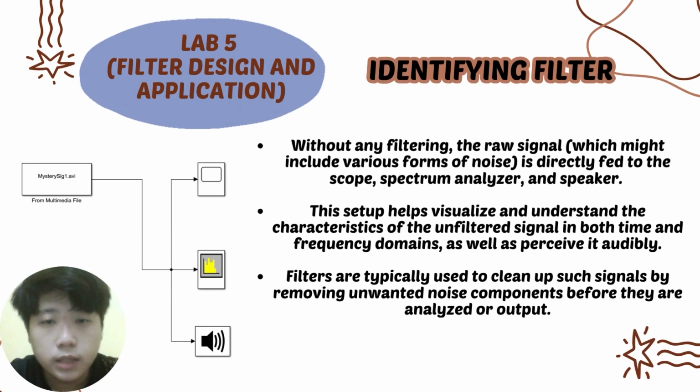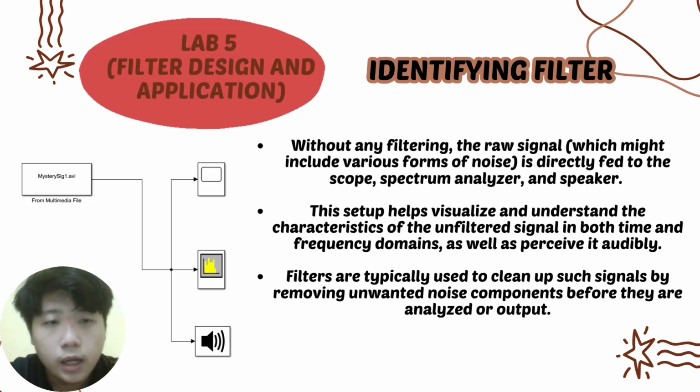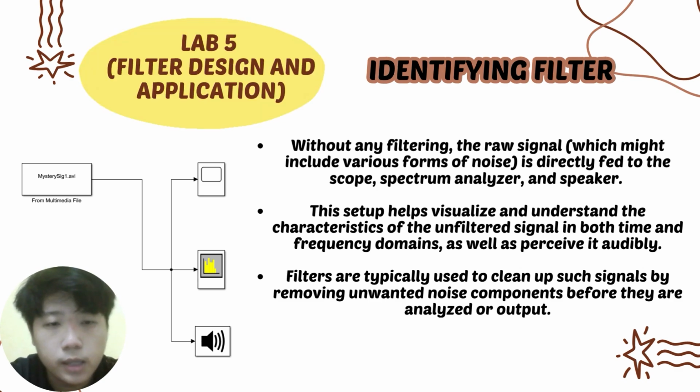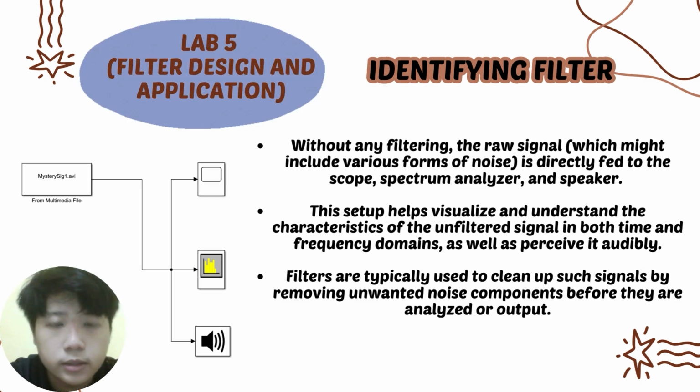So first of all, task one of LAB-5 is to draw the block diagrams for the simulation, as shown in the diagrams. Without any filtering, the raw signals, which might contain various forms of noise, are directly fed to the scopes, spectrum analyzer, and speakers. This setup helps visualize and understand the characteristics of unfiltered signals in both time and frequency domains, as well as perceive them audibly.